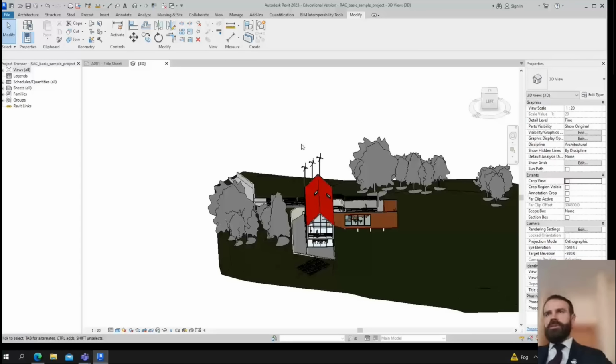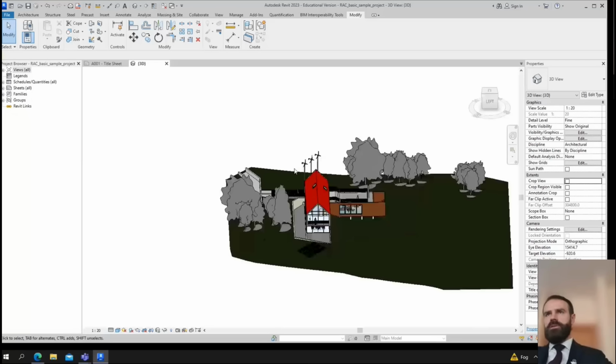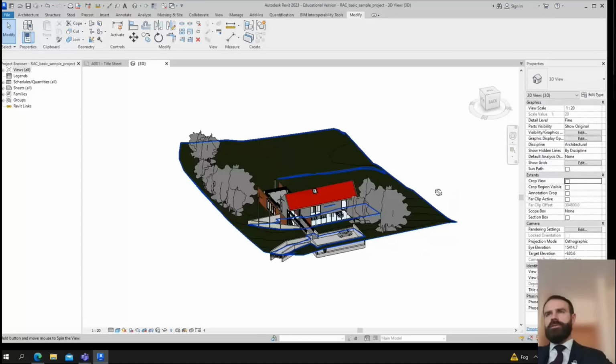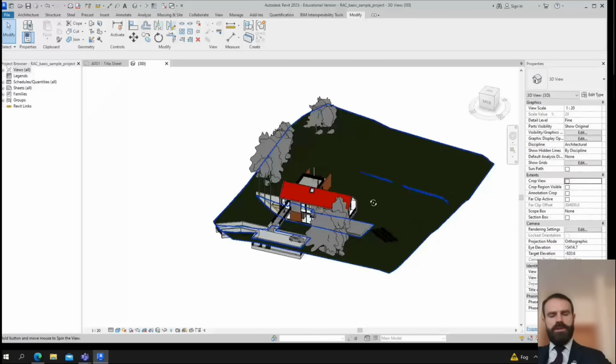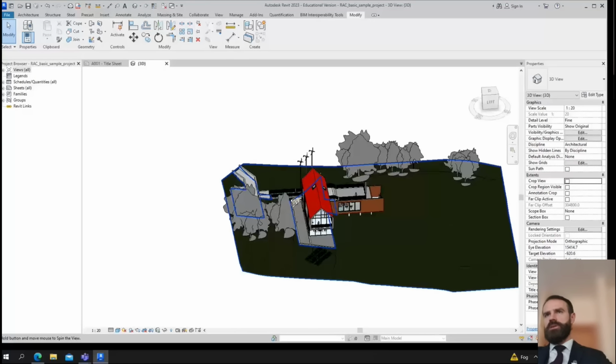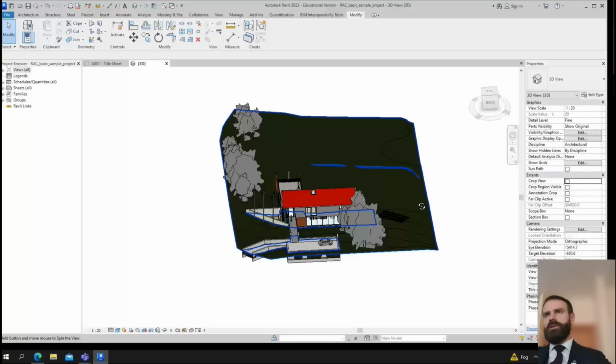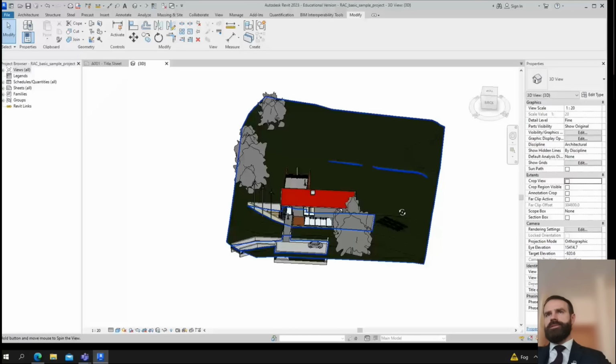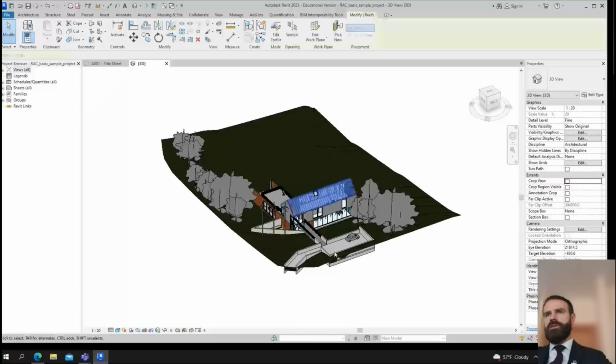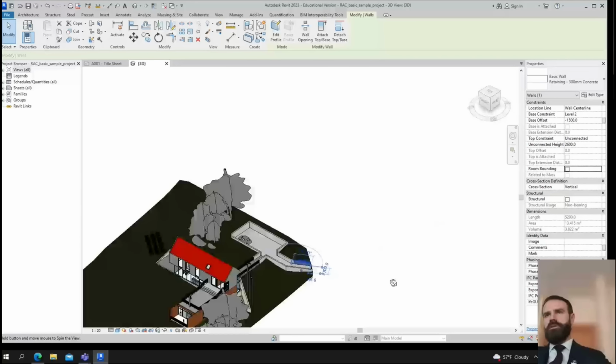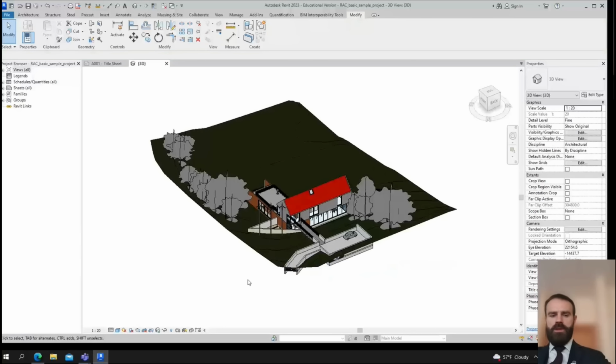and it goes like that. So rotating mouse wheel zooms in, zooms out in the 3D model. If I click shift button, and click mouse wheel, the model will rotate along the axis. If I select object, it should rotate along the selected object.